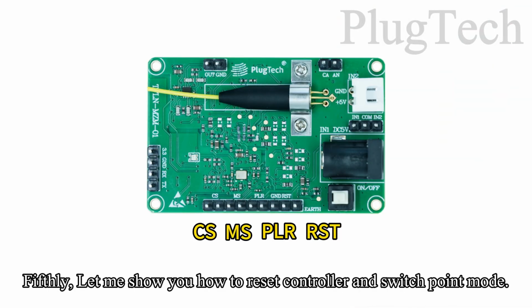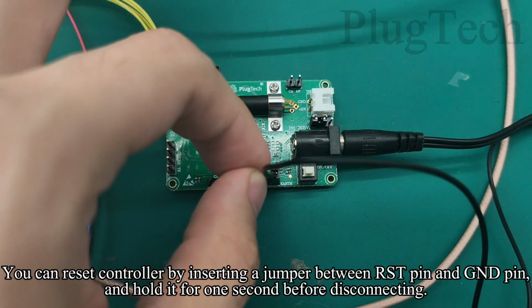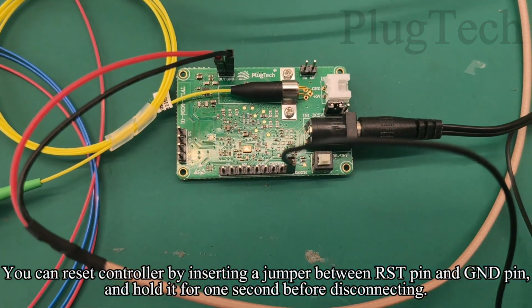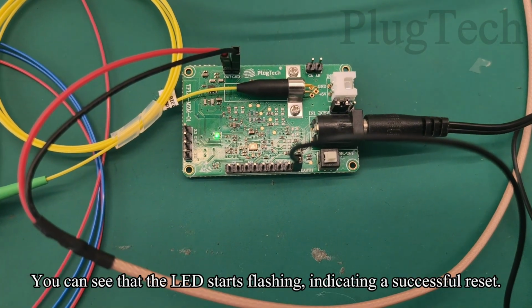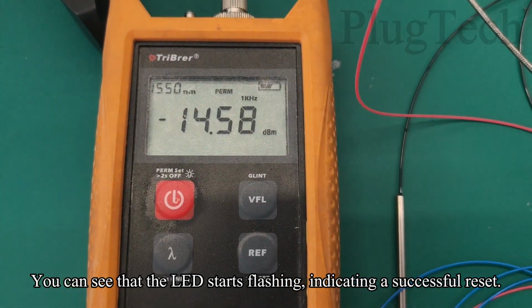Fifthly, let me show you how to reset the controller and switch point mode. You can reset the controller by inserting a jumper between the ST pin and GND pin and holding it for 1 second before disconnecting. You can see that the LED starts flashing, indicating a successful reset.